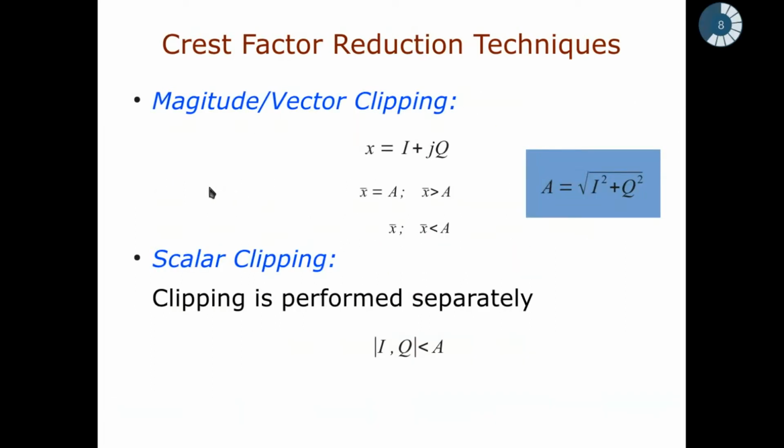Now we are going to see how we are going to limit this overlap of amplitudes into the other frequency band when you're performing OFDM. So the simplest thing that you can do is reduce the dynamic range, and by reducing the dynamic range, what we mean is that whatever amplitudes are going to overshoot the required linear range are going to be clipped.